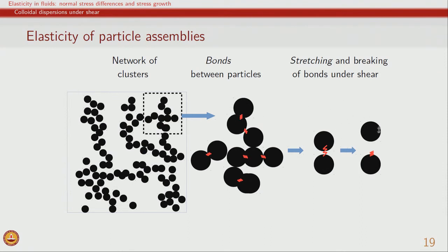So, therefore, there is again an elasticity and recovery possible with such bonds between particles. However, if the strain rate which is applied is large enough and the deformation therefore applied is large enough, the particles will actually separate. So, in this case we will again see the overall viscous behavior, and the overall viscosity or the stress required to move may appear to be smaller.